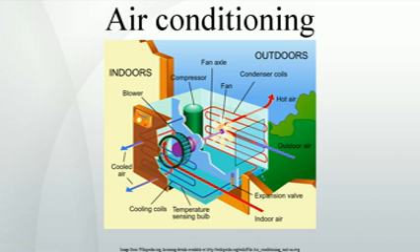This cycle takes advantage of the way phase changes work, where latent heat is released at a constant temperature during a liquid-gas phase change, and where varying the pressure of a pure substance also varies its condensation and boiling point. The most common refrigeration cycle uses an electric motor to drive a compressor. In an automobile, the compressor is driven by a belt over a pulley, the belt being driven by the engine's crankshaft, similar to the driving of the pulleys for the alternator, power steering, etc. Whether in a car or building, both use electric fan motors for air circulation.